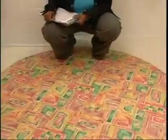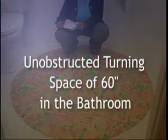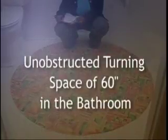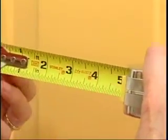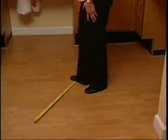Now we will see if we have an unobstructed turning space of 60 inches in the bathroom. And as you can see, we do have an unobstructed turning space of 60 inches in the bathroom. In addition to taking the measurement of the unobstructed turning space with a 60-inch round plastic tablecloth, you can also use a measuring tape. We will show you how to measure the unobstructed turning space using a measuring tape when we go into the kitchen.